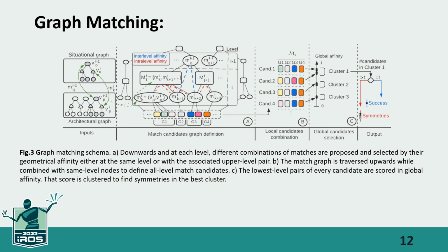Once the A graph is generated and the robot starts to generate an online S graph, the incoming S graph is matched with the entire A graph using our novel graph matching algorithm. The rooms of the A graph and the S graph and their subsequent planes are matched to each other based on their geometry. Once a geometrically consistent solution is found, the robot uses this information to perform global localization.